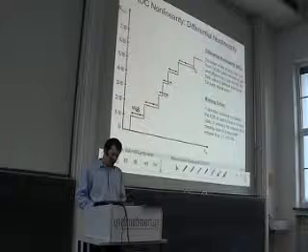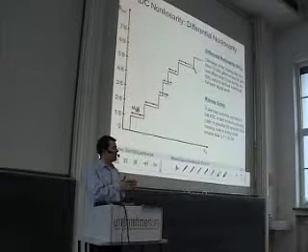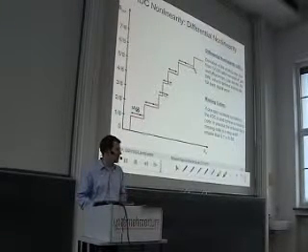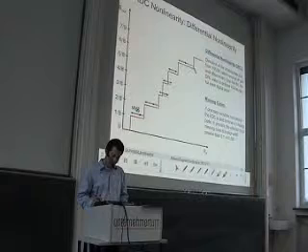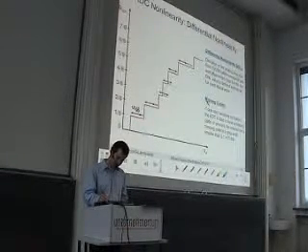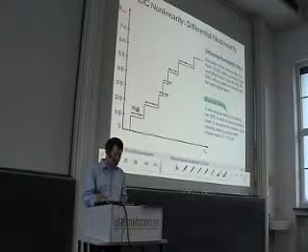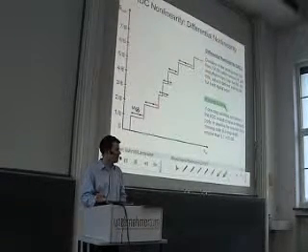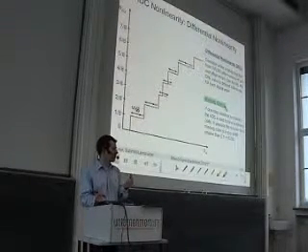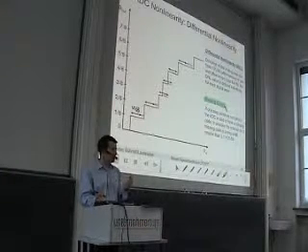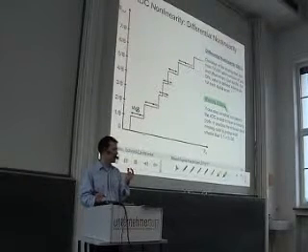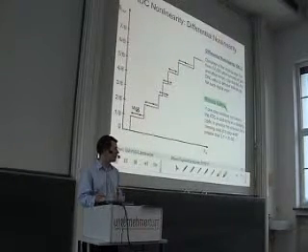One point is the correspondence of what we had in the monotonicity in the field of the ADCs. And there is something similar which we call a missing code. The missing code occurs if one step vanishes completely. So if the differential nonlinearity at one point is minus 1 LSB, so if the difference between the actual step and the ideal one is minus 1 LSB, then one step vanishes